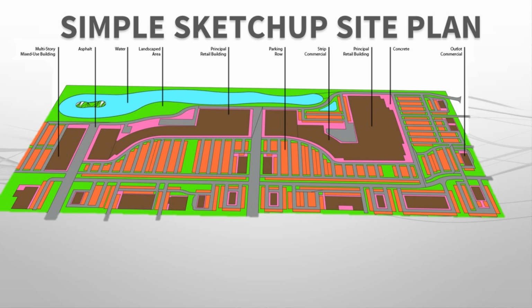Collada is the format I think that most people would utilize to go back and forth between 3D products. It's been my experience that KMZ between SketchUp and CityEngine is the best way to do this. So we place this in as a KMZ. The KMZ is geo-referenced, so from SketchUp placing it into CityEngine, it's going to put it into the exact spot on the Earth.